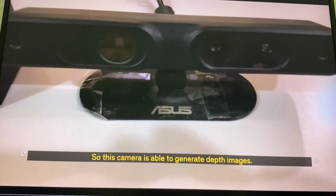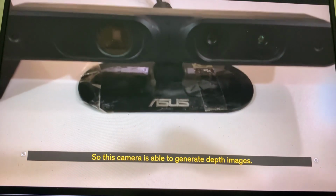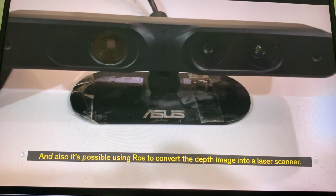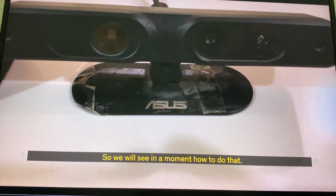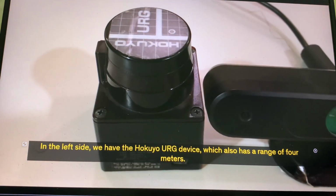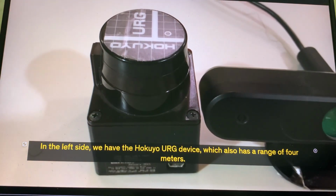So this RGB camera is able to generate depth images, and it's also possible using ROS to convert the depth image into a laser scanner. We will see in a moment how to do that in ROS. On the left side, we have the Hokuyo URG device, which also has a range of 4 meters.